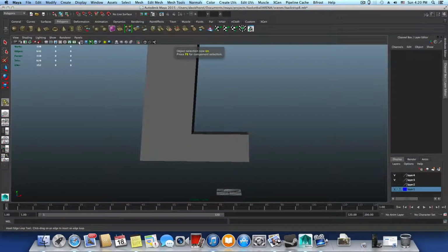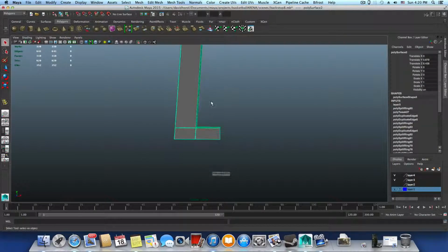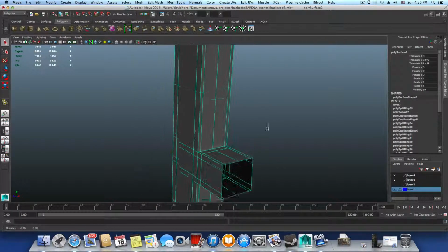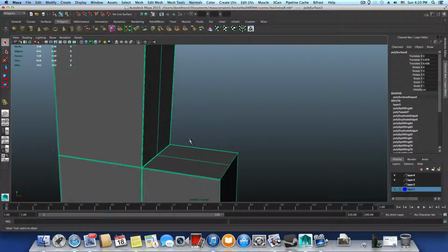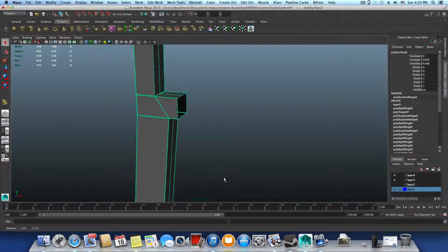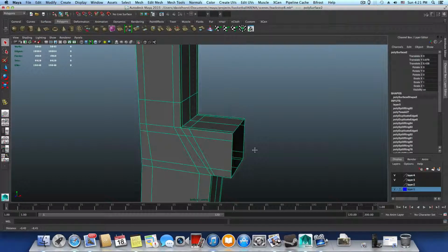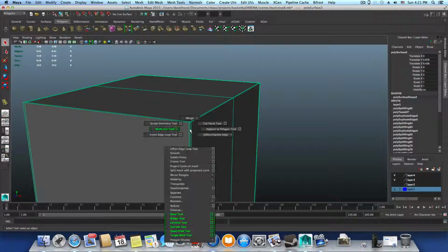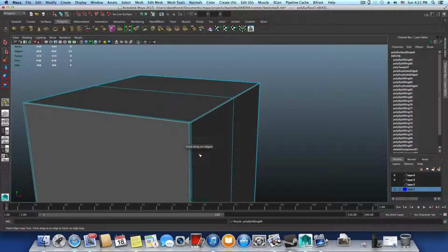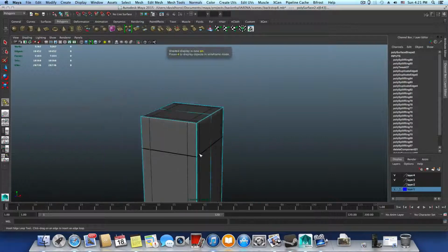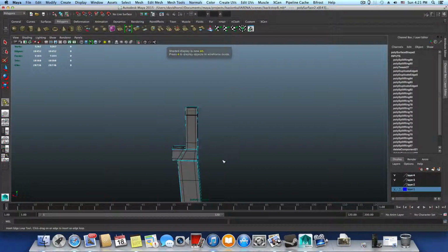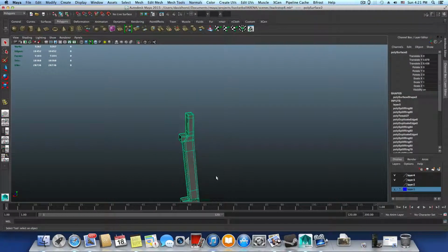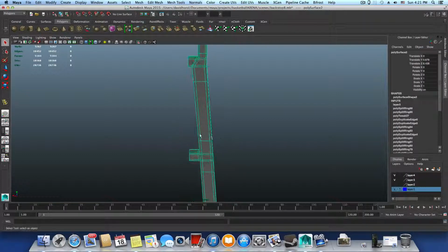So you can visually see all those little problems, and if you see that it's not as sharp as it should be, that means that at some point an edge loop has been missing. So press 3 now and take a look here. You can see this also appearing here. Something is just wrong here. We are missing the top one, okay? That one. Now everything looks sharp, right? Press F8 because it's on modify mode, making sure again that everything is correct.